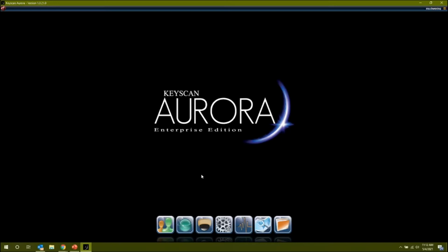So for the video integration in particular, we have a couple of different ways that we can utilize that. If you have someone that's actively monitoring the system, for example security personnel, and you have the events set up so that if there's a door forced open or some other violation for the system, we can automatically pop up that video feed, and then they can see that live video feed.